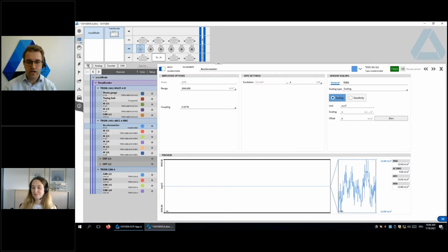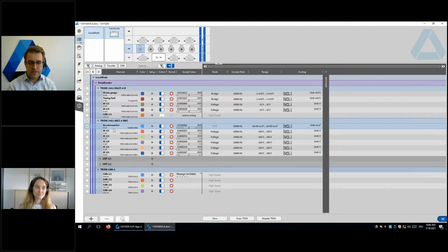Our CPAD hardware got some love too. For those who don't know what a CPAD is, these are small additional hardware bricks which are being used for slow or static measurements. They communicate over CAN, and until now it was necessary to use DBC files to implement them. But now this changed. So now it's really easy to use, even easier than before. Now no DBC file is needed anymore to decode messages.